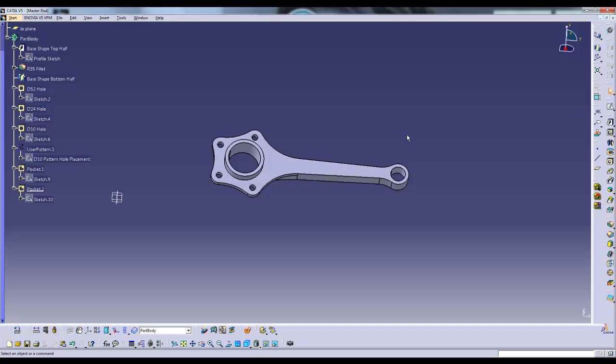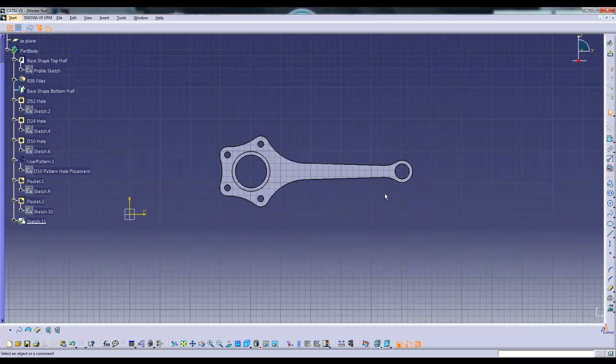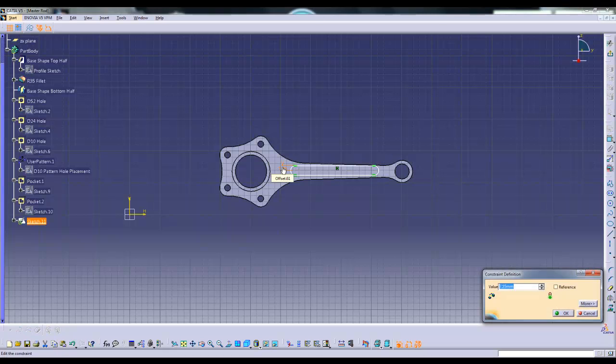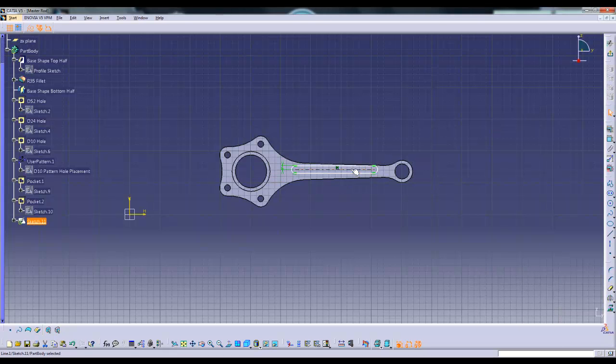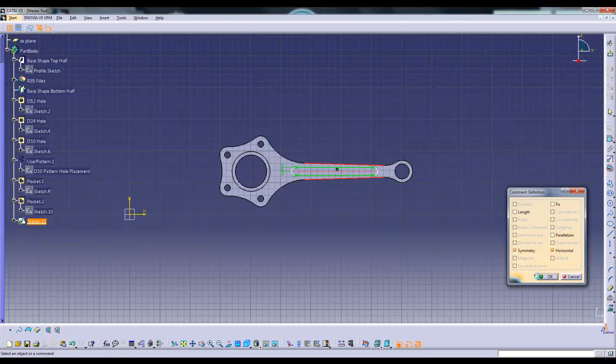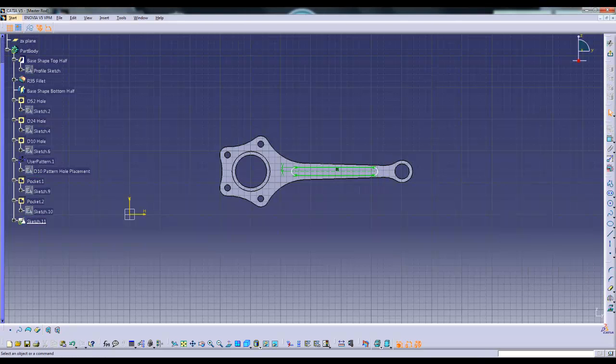Enter into the top surface once again. What will be created now is the elongated hole. Under the square command, there is the elongated hole command. Change the radius as follows to 6 millimeters. For ease, create a point concentric to the right circle.